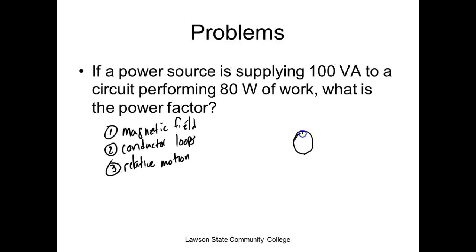So if I had these conductors, they call it a squirrel cage. So this has rings in it. That's the conductors. And what we do is we come up here and we put AC on this. This flux goes through there. So if this is a north, this is going to generate a south. And what would they do? They would attract each other, right? You understand? Well, if this goes south, this generates a north, they would attract each other. And that's the way a single-phase motor would run.